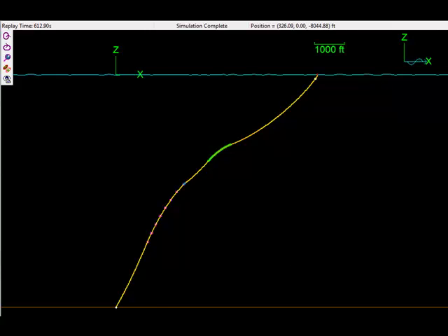This is the general nature of the riser in the 2,350 metres water depth site for buoy 4 in the Mediterranean off Cyprus. The buoy up here is being dragged by a combination of wind, wave, and current forces, and in this part of our presentation we're interested in an area of the riser here which surprisingly sees some compression, and an area of the riser here just before the green buoyed area.